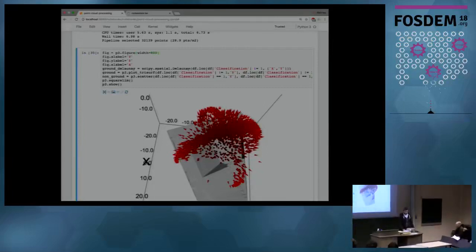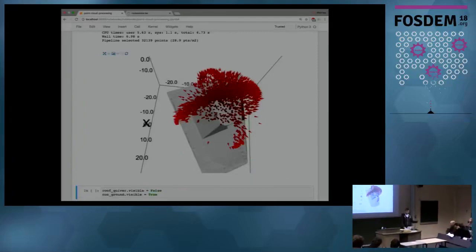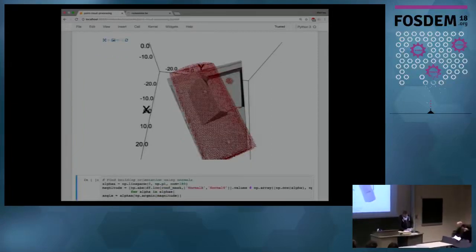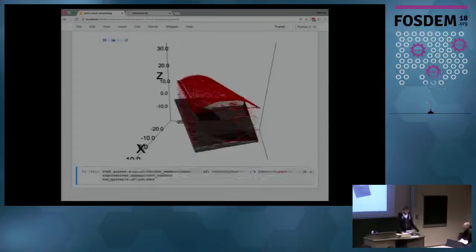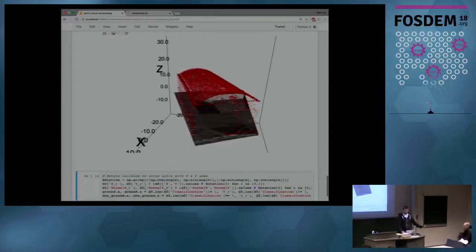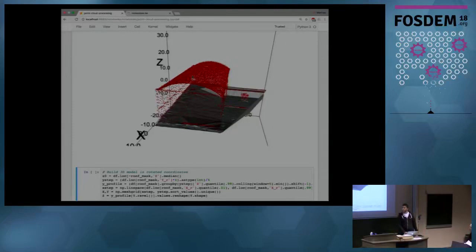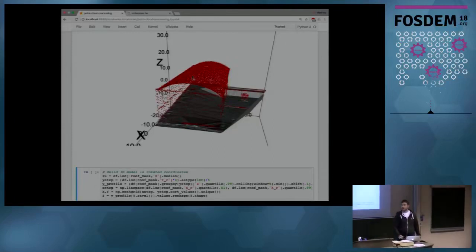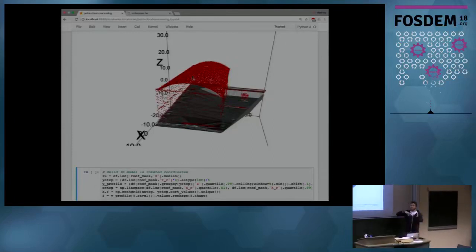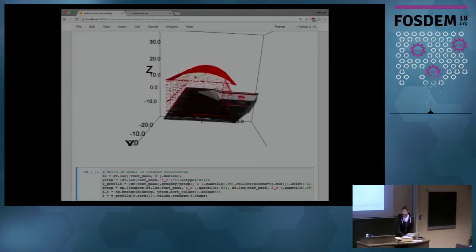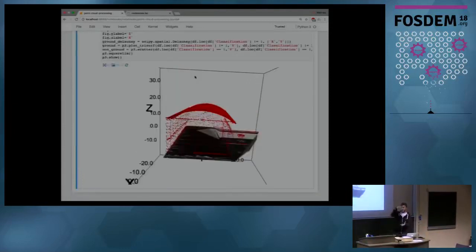So this I can use now to basically infer, let me put those points back to where they were, infer the orientation of the building and figure out how I can rotate the building in order to align it with the axes. No, this is inferred from the raw point cloud data by looking at the points around them. This is all PDAL. PDAL provides you with the normals, some eigenvalues to tell you if it's fluffy or flat, and yeah.